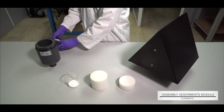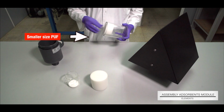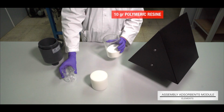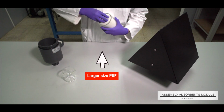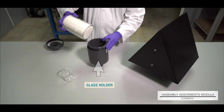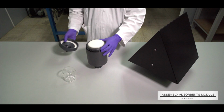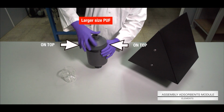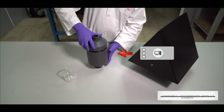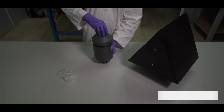Preparation of the adsorbent module starts by taking the glass cylinder and placing the smaller PUF at the bottom. Then 10 grams of the polymeric resin are added, and finally we place the biggest PUF at the top of the glass cylinder. Final step consists of the placement of the glass cylinder, containing the adsorbent, inside the adsorbent module. We will make sure that the biggest PUF is always placed on the top part. Finally, we will screw the cap, put an identification label, and the device will be ready to be used.